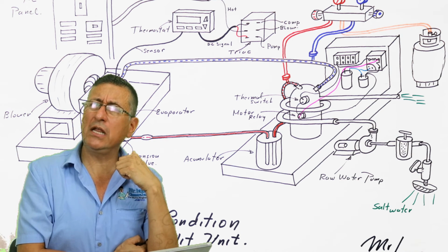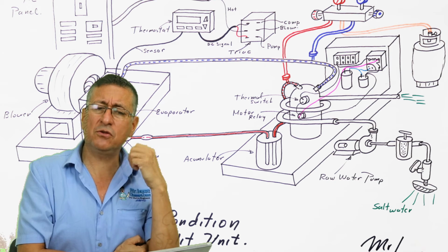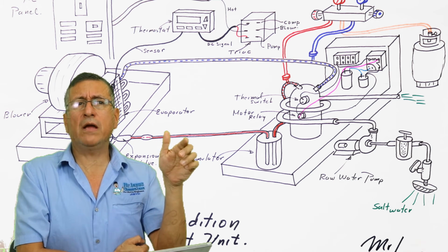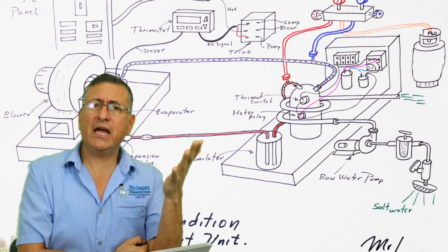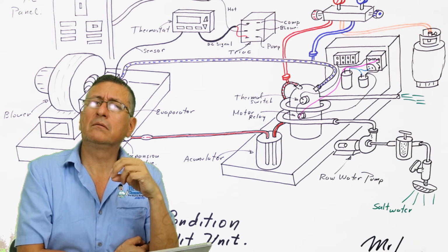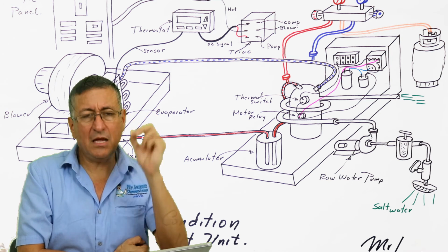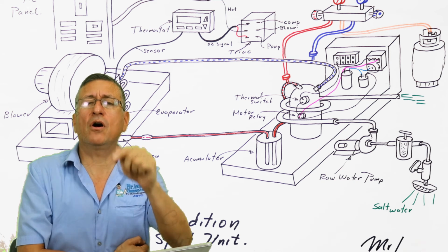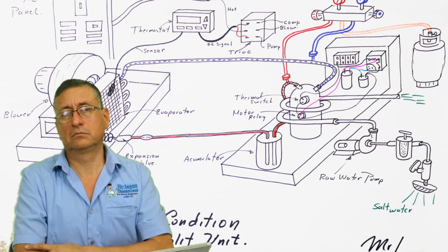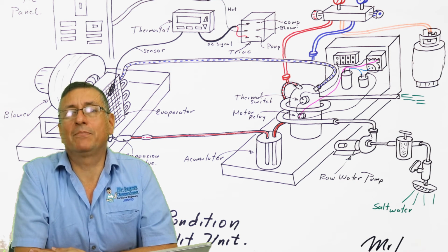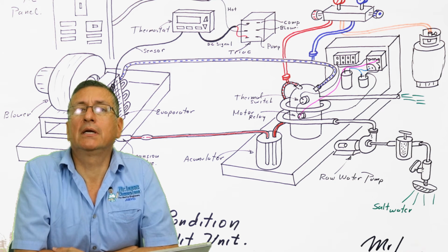What happens if suddenly you hear that the compressor every 3 minutes starts and works 5 minutes and stops and starts again and stops? Too quick. This is the typical symptom that the level of refrigerant is too low. Yeah, cycling in the compressor.